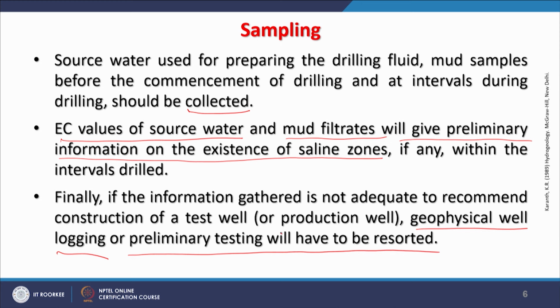Production well, this term also comes from the oil industry, or for water also. Before finalizing, as I was saying, for domestic consumption for one house or two or some colonies, such expensive solutions, geophysical well logging, may not be required. But if it is for industry, then all these methods have to be adopted, because for certain types of industry, continuous water supply is required, and therefore after the drilling, geophysical well logging will also be required, so that the well becomes highly reliable in terms of productivity.